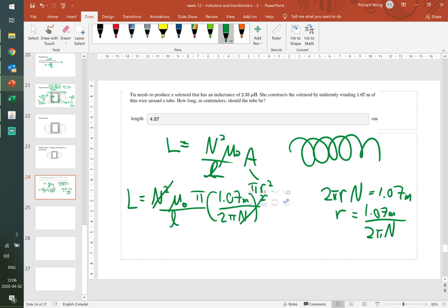And while I'm here, Finn's question about welding machines. It depends on which kind of welding machine you're talking about. Some, like an arc welder, you've got to make an arc, right? So to have an arc, you need high voltage. For resistance welding, like a spot welder, you would need high current, since power is equal to I squared times R. So it depends on what kind of welding machine you're talking about, whether you want high voltage or low voltage. But yes, in order to step up or step down, chances are you would use some kind of transformer. And yes, I did do a co-op job once upon a time in a welding company. That's why I know so much about welding, more than you would expect.